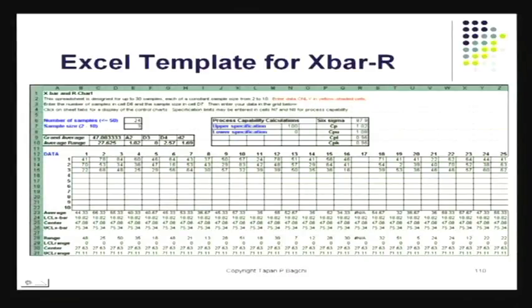And also, I get very disturbed when control charts are prepared after 7 days of data collection. If it is done almost immediately, you don't need to do a lot of calculations. You can get your chart done very quickly. I was in a factory, and this factory had a built-in SPC system. It was like Excel, but it was built into that automatic machine that was there.